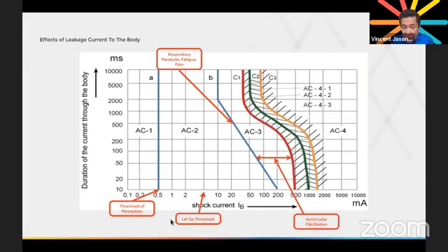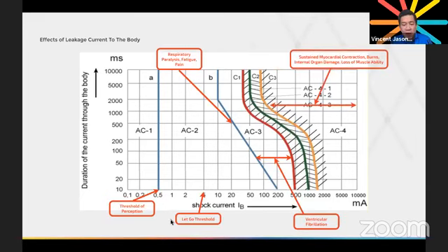And depending on your body impedance, anywhere between about 70 milliamps to about half an amp, ventricular fibrillation. So yeah, it becomes very, very dangerous now. Now, this one above 2 amps wasn't exactly in the IEEE. I just read this somewhere, but it looked very, very interesting. But you would have sustained myocardial contraction, burns, internal organ damage, loss of muscle ability. So it's probably going to hurt. That's the thing.